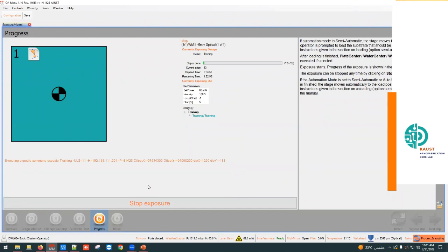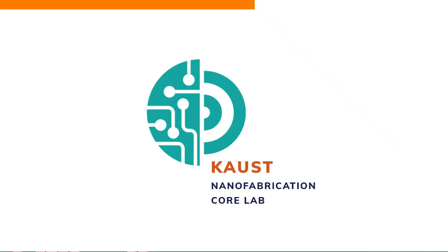Because you asked me about masks and I said no, you cannot reproduce 300 nanometers onto a mask. You can just reproduce it in the way that I will explain to the users that really need to achieve this resolution, because believe me, that is not obvious. You need a silicon wafer coated with an anti-reflective layer, and on top of this, a high resolution photoresist. Then you can achieve that.